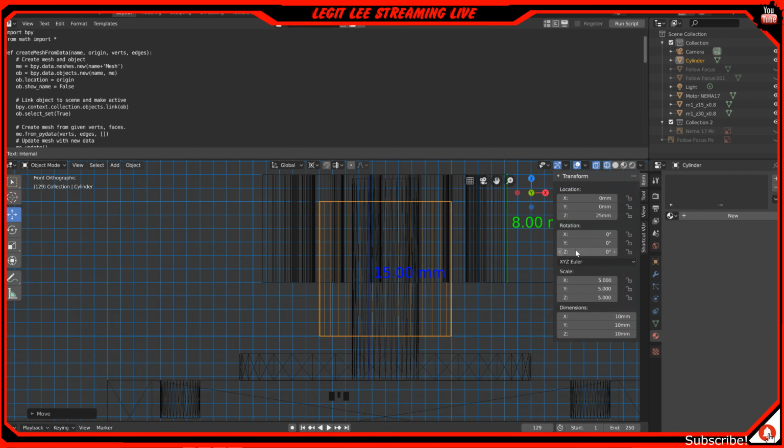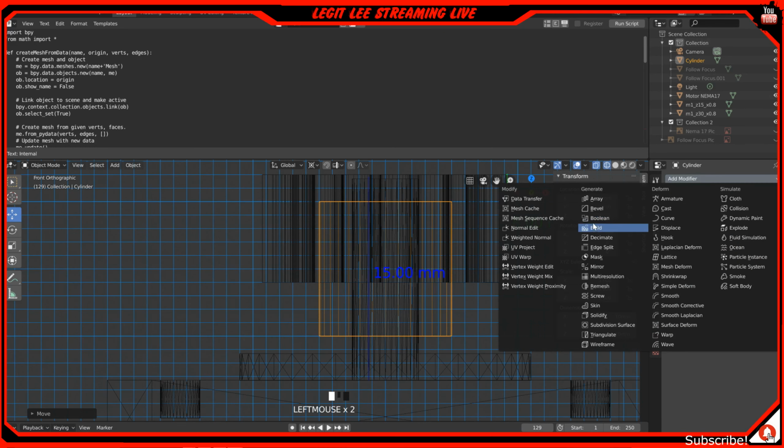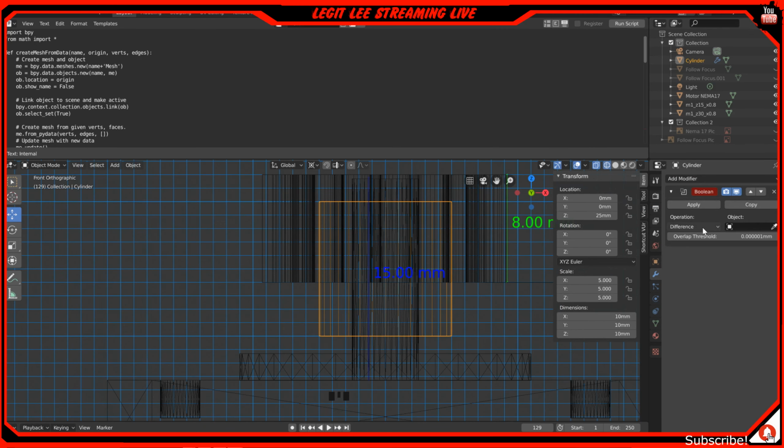So that's good. So what we're going to do here is actually group these together through a Boolean modifier. So we go here to the wrench, add a modifier, do Boolean. We're going to do union. I'm used to saying group because of Tinkercad. But union, hit this little eyedropper icon, and we're going to click on this guy right here.